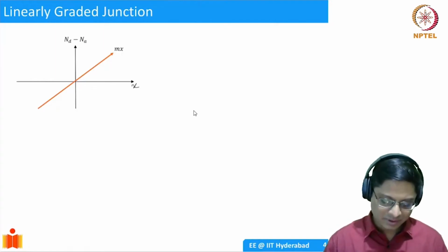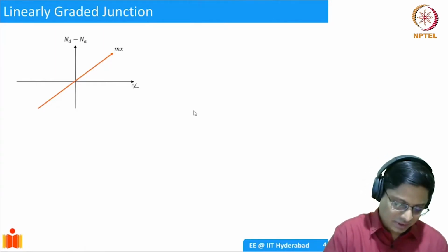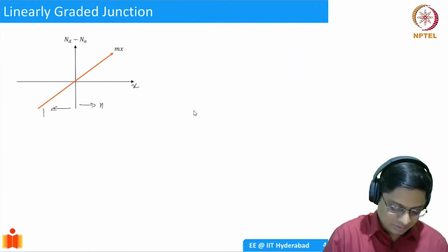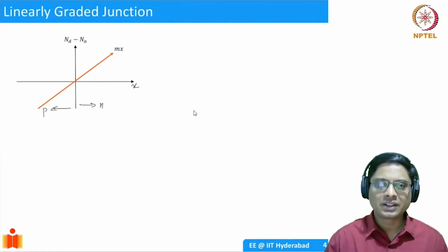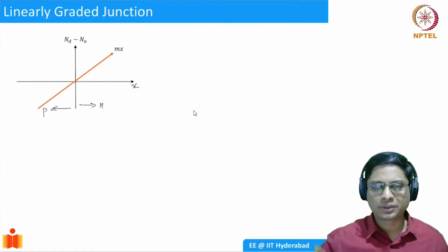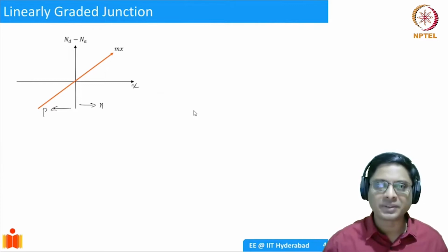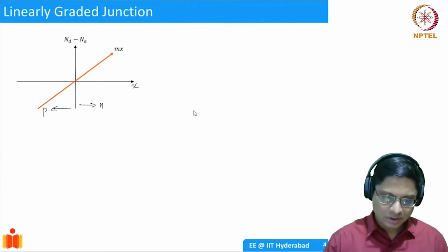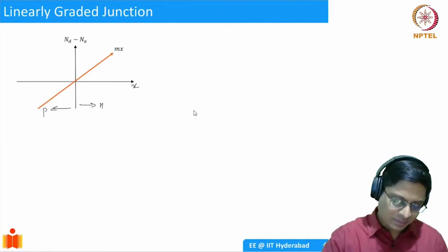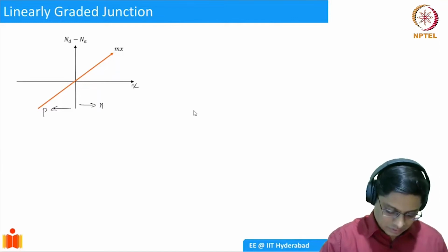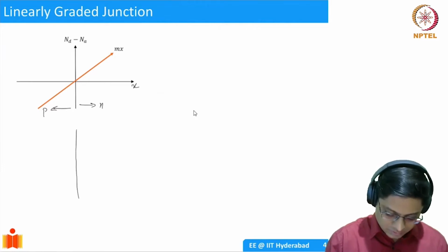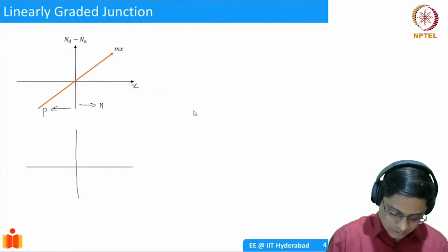Still, you would have the same thing: this is the N-type region on the left side here, and this is P-type. You still have excess carriers, but at the junction you have relatively few free charges, while you still have a lot of excess on the other side in the bulk of the semiconductor. So they're going to cause some diffusion. How will the space charge profile look? Since there's going to be some diffusion, you can draw the space charge versus X.